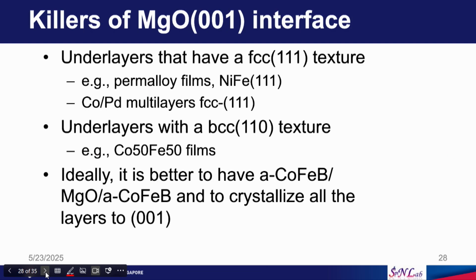Okay, so, as I mentioned, if you have materials with the FCC 111 texture, it is not good. So, we have to break this FCC 111 or BCC 111 texture, but we should focus on getting the BCC 001 crystal structure. Okay, that is important.